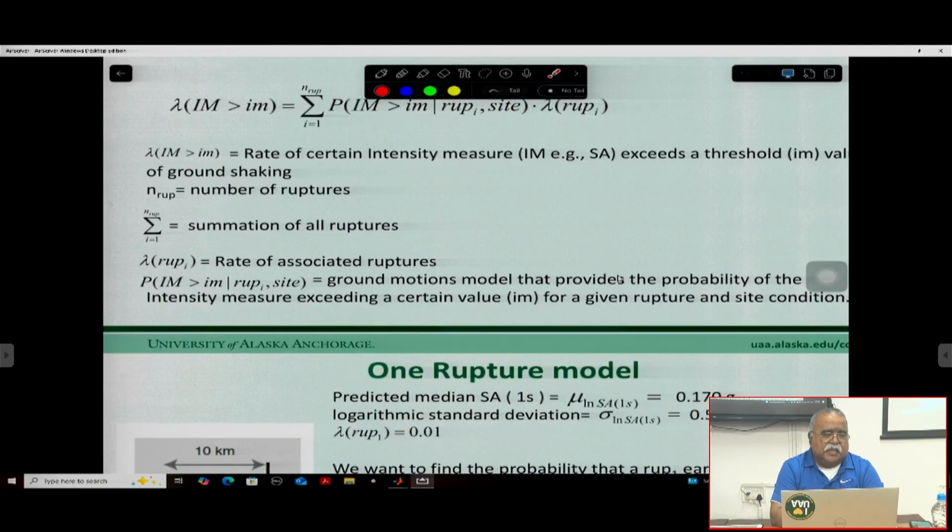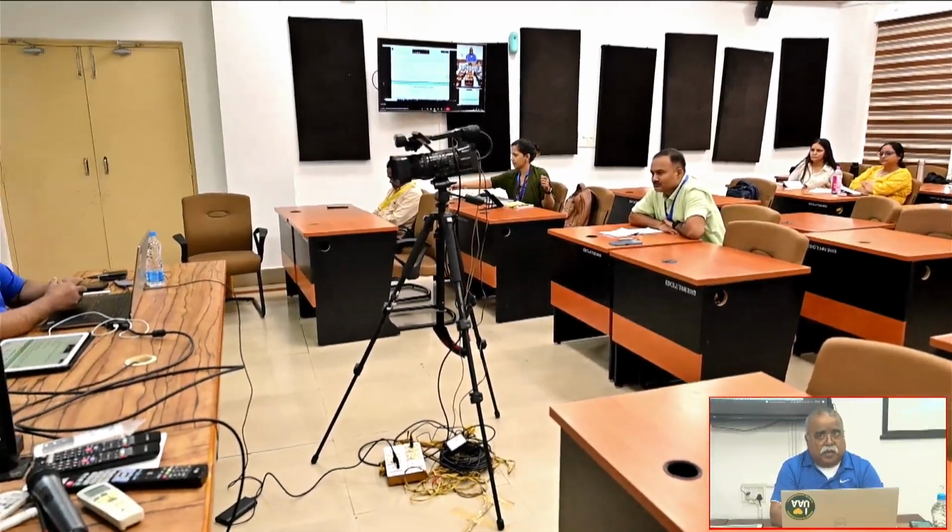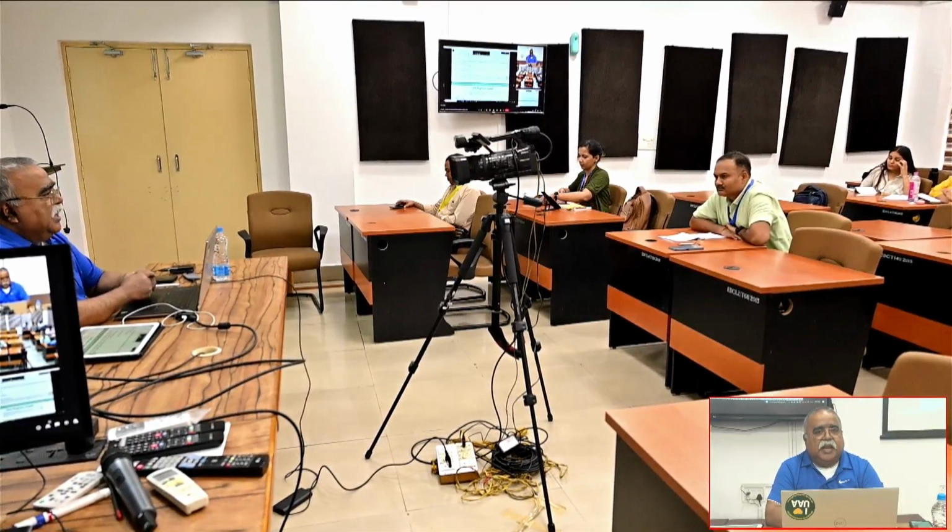Compared to DSHA, PSHA is much more elegant and takes care of all the factors of the fault ruptures and the magnitude possibilities in a much better way. Better way means in a probabilistic way, right? So that's the main emphasis.